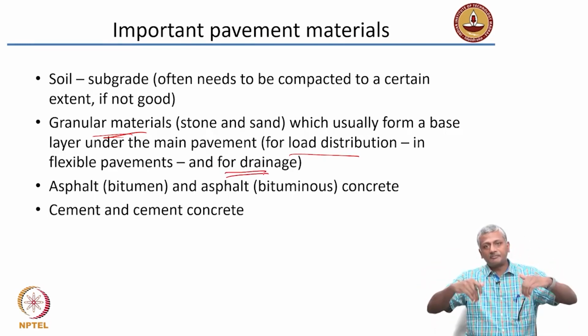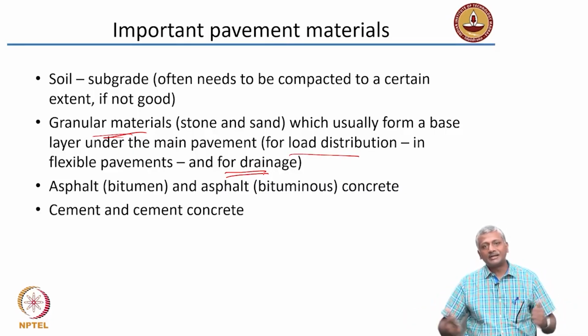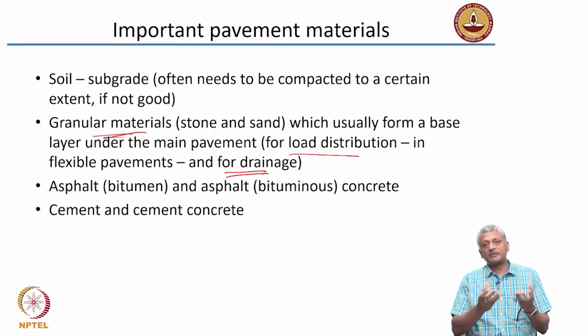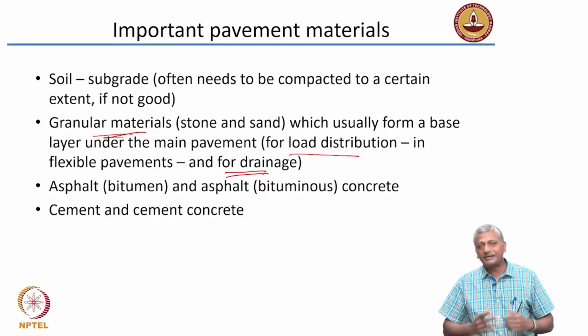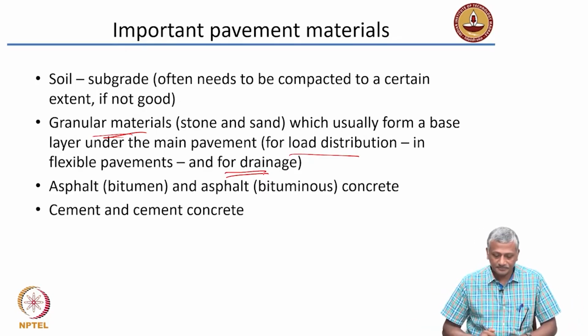If any water enters the pavement, it has a chance to get out from this layer, which is made with granular materials, because it has a lot of gaps inside. So, it will let out the water and drain the pavement quite easily.